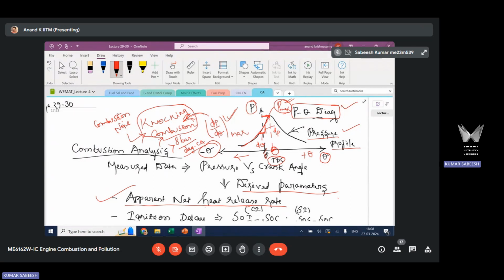That is generally a threshold value above which you can say that the combustion is abnormal or knocking, because you can hear the knock. It's audible to the human ear, that I already discussed. So combustion noise will be high when the pressurization rate is high, but we need to have an optimal pressurization rate, because this represents the burn rate, right? Pressurization rate is a resultant of the burn rate of the fuel air mixture, right?